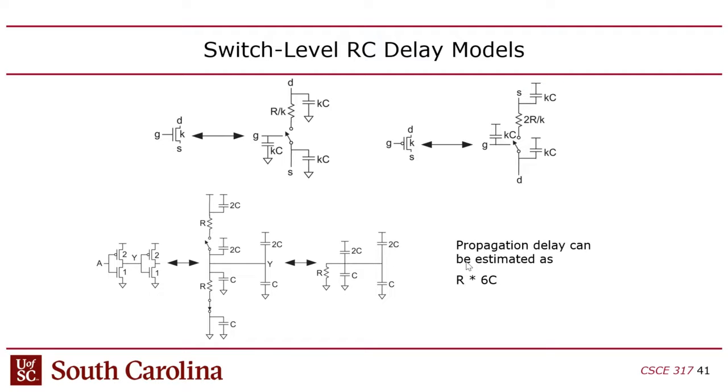They write the transfer function like we did in the control theory part of the course, and then they go from the S domain to the time domain using the eigenfunctions like we did. From that, they calculate the time it takes to drop or to raise. So they basically calculate the S domain equation of this RC network, and then do an inverse Laplace transform.